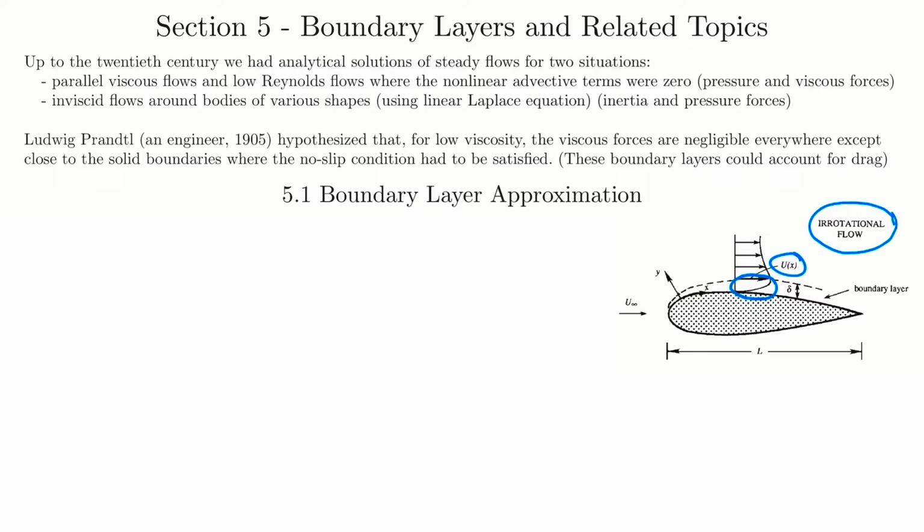So we're going to be considering the case of a boundary layer that's next to a wall. We're going to use a curvilinear boundary layer coordinate system. X is going to be along the surface, like shown here, and Y is going to be normal to the surface. We're going to call this irrotational flow in the inviscid part, farther away from the wall. We'll call that the outer problem, and I'm going to refer to the flow within the boundary layer as the inner problem. Now, as shown in the figure, the thickness of the boundary layer varies with X, okay?